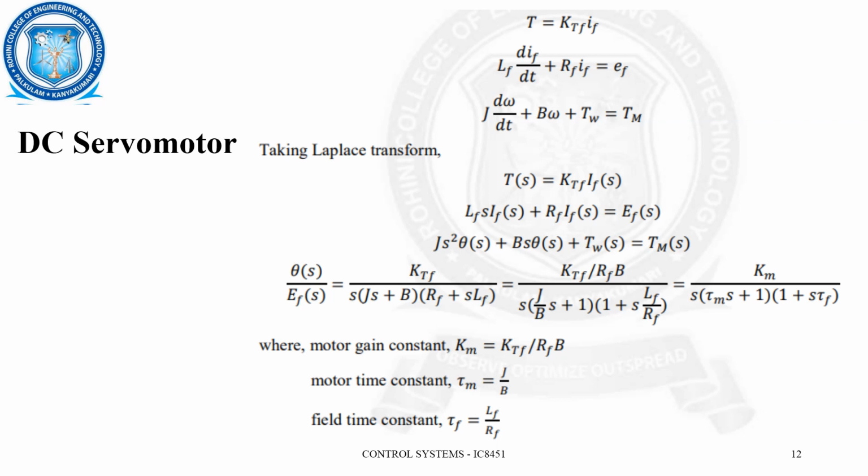While comparing with the armature controlled system, there we have the back EMF effect since armature voltage is applied. But in the case of the field controlled system, the back EMF impact will be negligible. So we are avoiding that equation, and so we have only three equations. On applying the Laplace transform to these three equations, the equations get transformed, and finally we can obtain the output theta of s divided by the applied voltage Ef of s. This is how we get the equation.